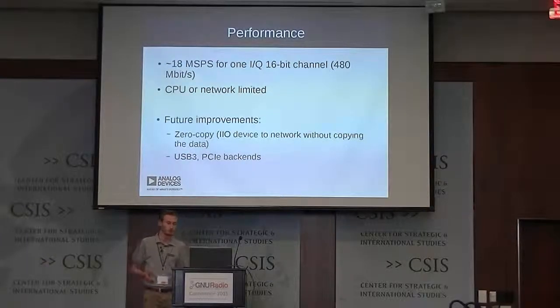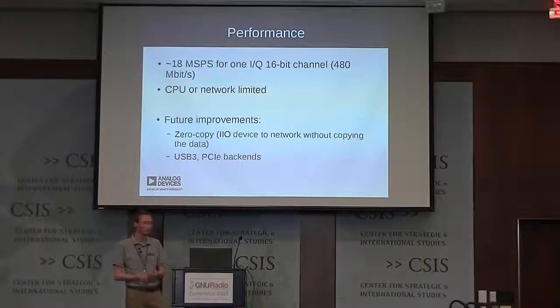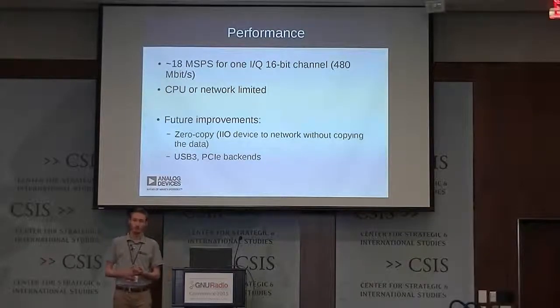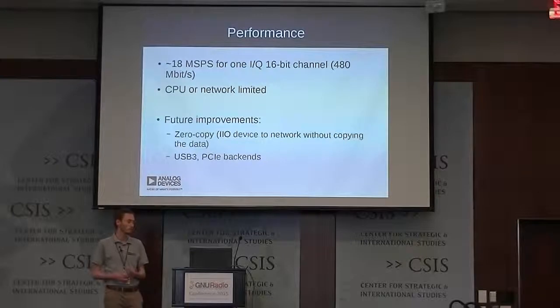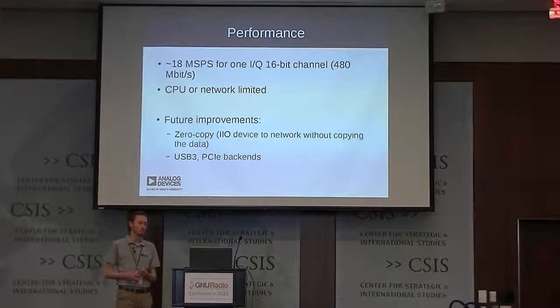On different boards, we are limited by the network, and we can get around 18 megasamples per second for one IQ channel. That corresponds more or less to 480 megabits per second, which is the maximum we can get on the network with a TCP connection.